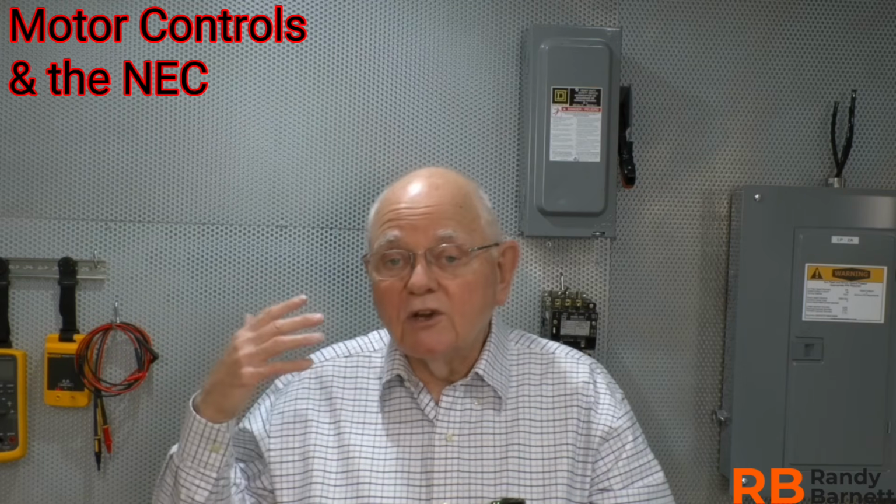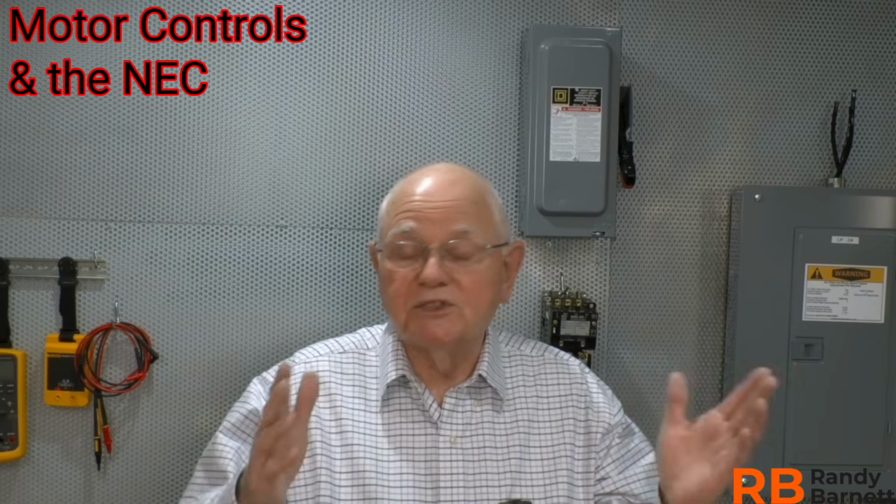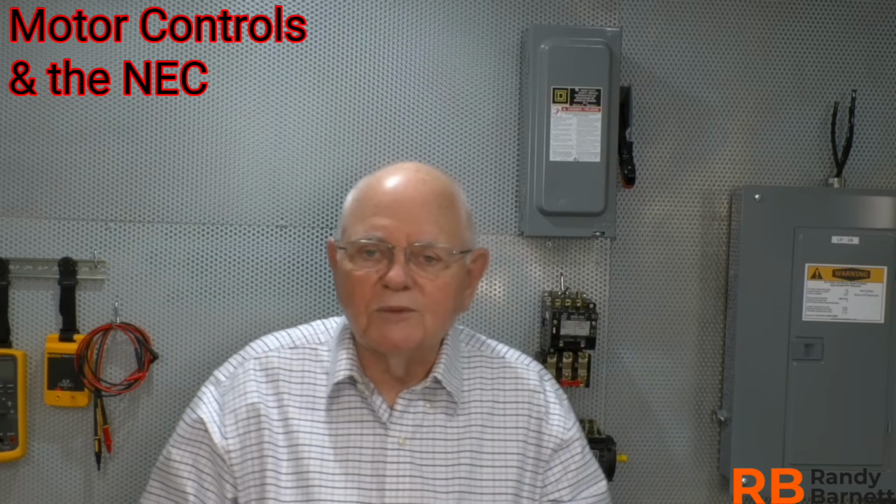Now, we have to remember that there are two separate circuits when it comes to motors and controls. We have the main power circuit, and then we have the control circuit. So let's start by taking a look at this main power circuit and see how the control circuit ties into that, and why the control circuit actually appears in a separate article than Article 430 on motors, or whatever specific article it is, for air conditioning and refrigeration equipment, motors, compressors, whatever it is that we're working on.